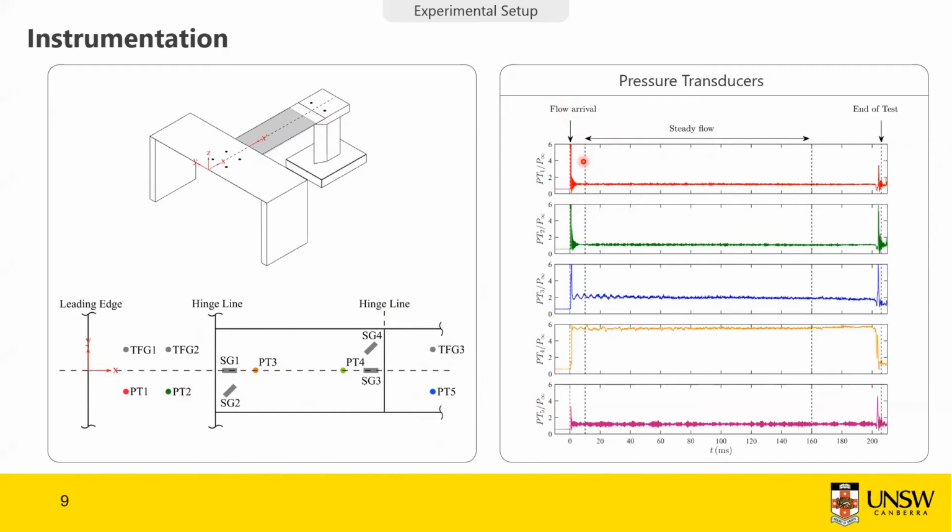So that is where the hypersonic core flow is fully established, because in this stage here it's getting developed, but after about 160 milliseconds, the hypersonic core flow starts to collapse. In fact, the total temperature is expected to decrease, and we cannot properly model the flow conditions using the isentropic relations, because we have problems after 160 milliseconds in terms of decaying total temperature.